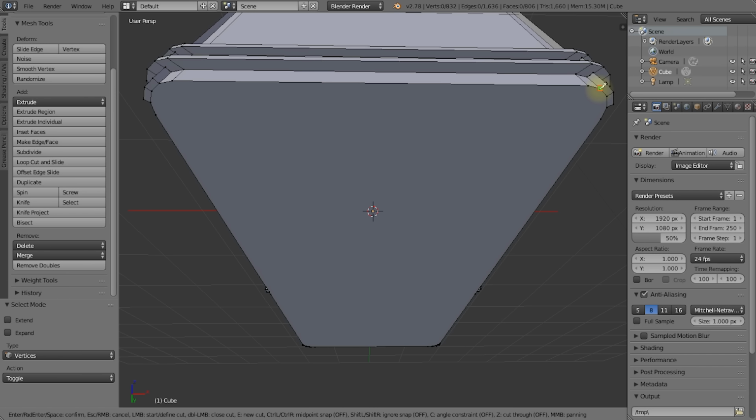Now let's press K to enable the knife tool. And let's draw some lines from the right to the left side here to essentially turn these into quads, like to kind of slice up our bottom face. So let's simply click on this vertex here over on the right hand side.